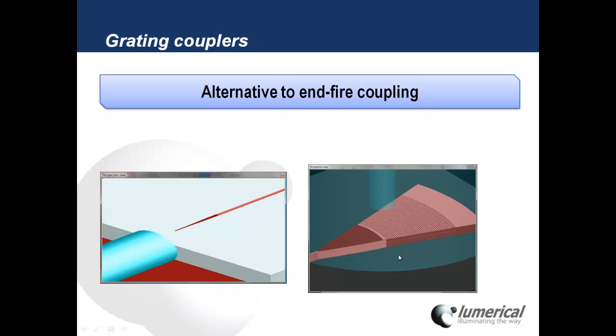The grating coupler gives you the opportunity to do vertical coupling of light, and therefore you can have a beam that comes in from above, or you can extract light vertically out of the chip. You can also use a fiber almost like a light contact at any position within the chip. So there are many advantages obviously to that in terms of the fabrication process and the number of places you can bring light on and off the chip.